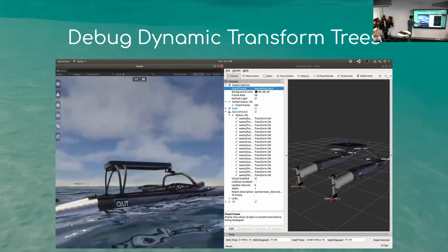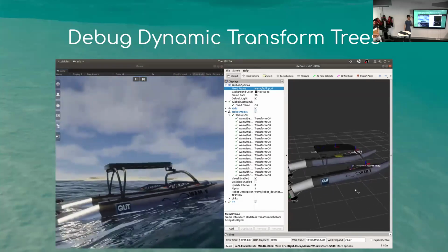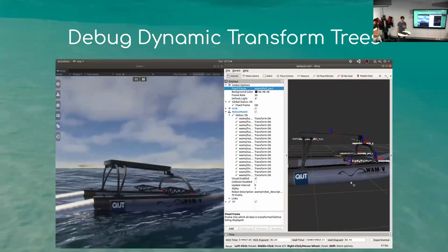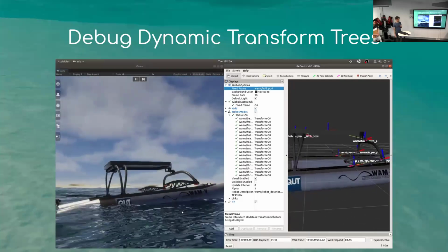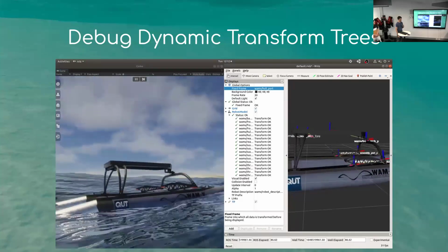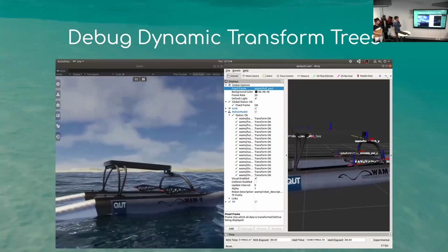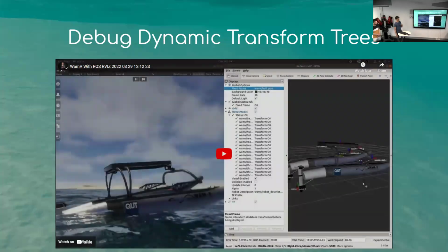The whole goal here is to have this platform here, which is where your cameras will be mounted, behaving as similarly as possible to how it would in a given sea state. And the only way to really get that is to have a reasonable simulation of all the joints in between the water surface and the platform itself, as well as the buoyancy of the pontoons.